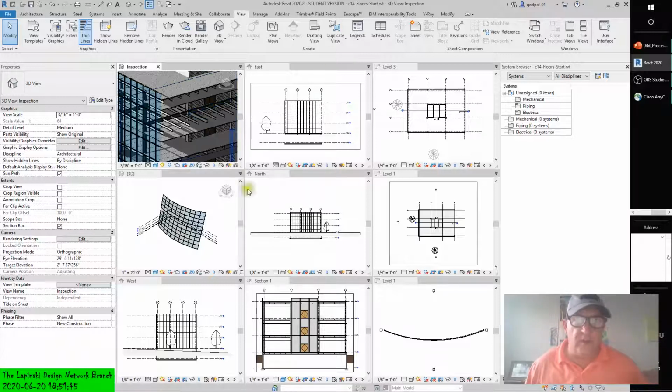So I just wanted you to orientate yourself to that, because we'll be creating a structural floor. Now, the structural floor is similar to a traditional floor, but has structural functionality, such as the ability to indicate span direction and to contain structured profiles. For example, you can specify a composite metal deck profile which will display in sections and details generated within your project.